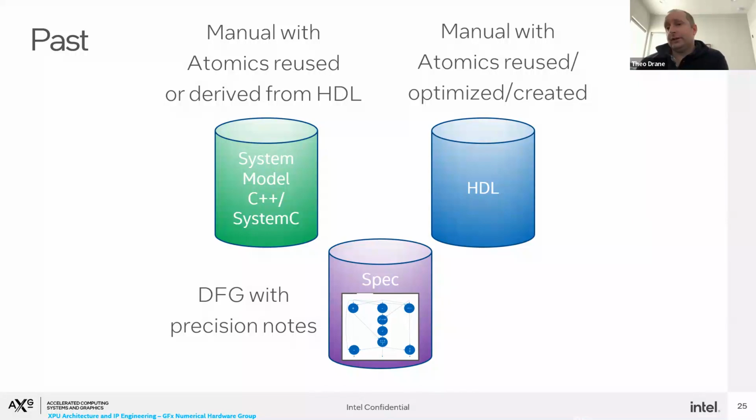The problem with all of this, of course, is note that the HDL precedes the C++, which means that whatever design process went through in this case, you have to go all the way through to HDL to then generate C++, and only then can you start seeing if you'll pass compliance. So basically, there are really no intermediate steps. There is no feedback loop until you have the HDL.